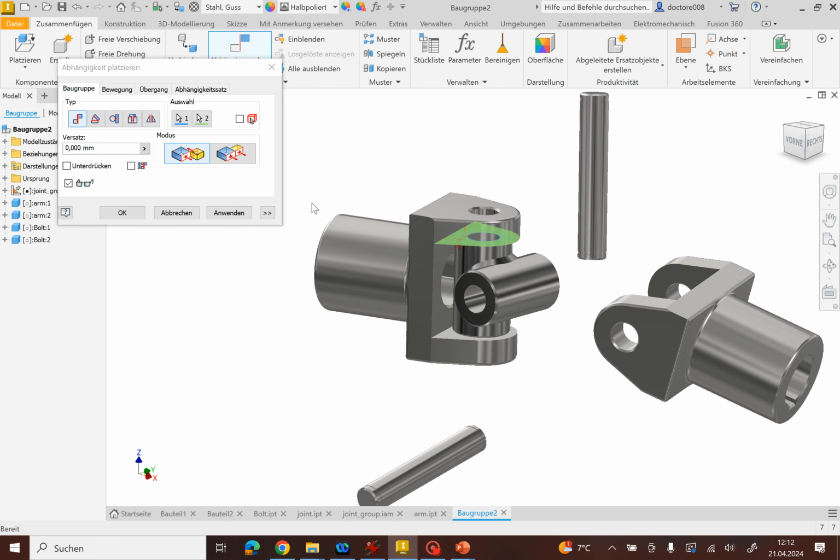But before we push the apply button, we need some distance here between them. You remember there was a distance of 0.2 for the movement. Therefore on this particular side we have a distance of 0.1, and that automatically creates a distance of 0.1 also here. So distance over here and here, and apply.